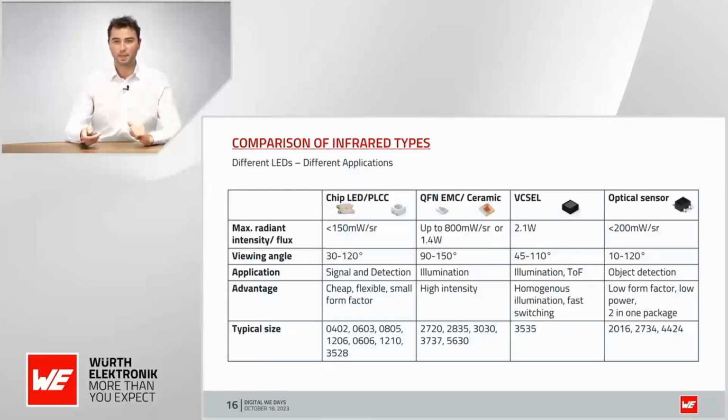on the part number. And so what is actually the advantage, and why would you want to use a VCSEL? Well, it is more expensive than classical infrared LEDs, but for certain applications you want a higher power, and then you can go to the VCSEL. They can give you a much higher power than normal infrared LEDs. And what's also important is they are much faster than normal LEDs. So you can switch them on and off really fast.